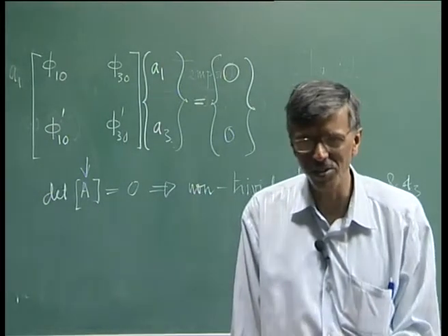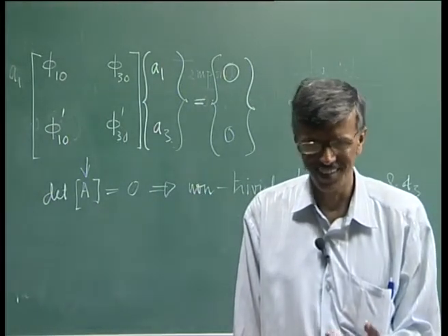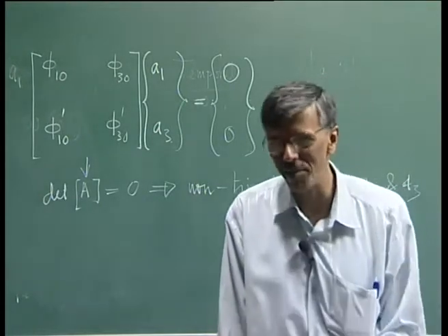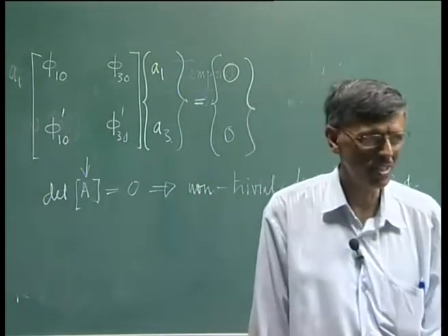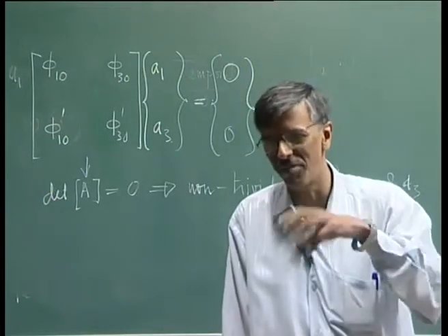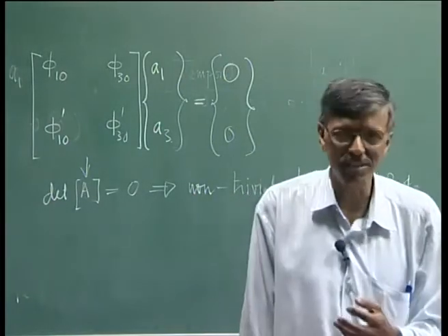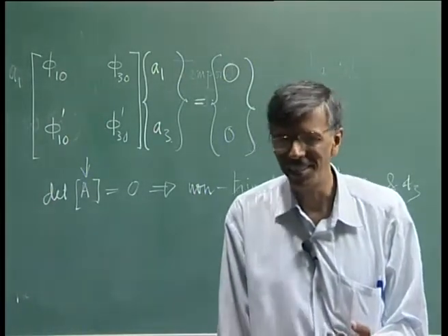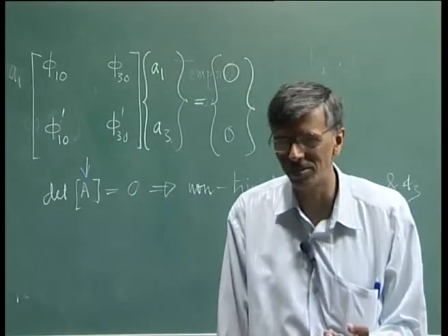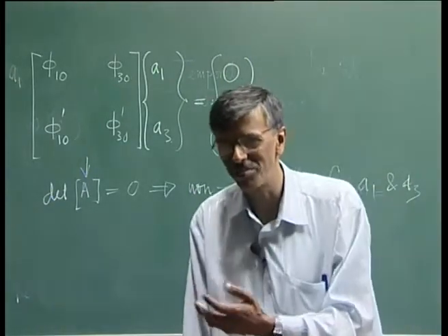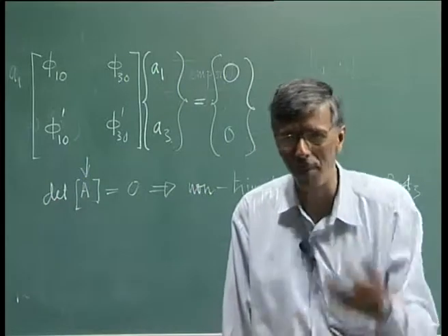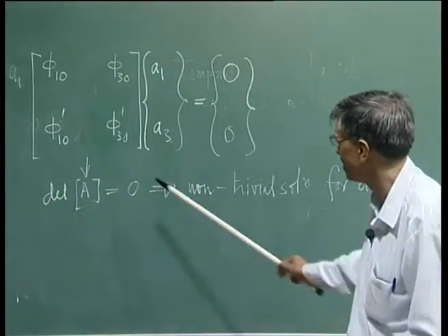So, division by 0 is a kind of state of amplification. If the determinant goes to 0, you are amplifying the numerator. That is what instability means: you have a vanishingly small disturbance, but the property of the system is such that you are amplifying it.